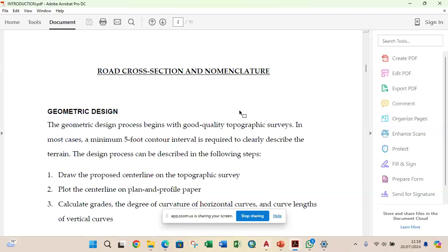But if you are going to a project and you know that you have a higher axial load coming on that road, and you anticipate that a lot of the vehicles will be heavy duty vehicles, you have to do pavement analysis and design using the axial load, together with your soil parameters, which are the CBR and all. You do your soil parameter analysis to come up with a thickness that can withstand that traffic. But the federal highway, they have done the research, and based on most of our roads, they propose a minimum 500 mm thickness can accommodate any axial load on the road.